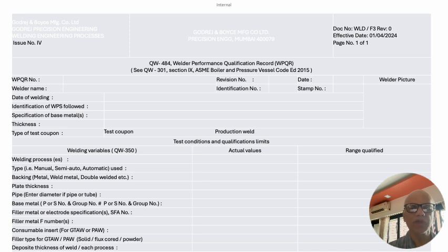Now the welder should be comfortable and should have confidence that in the given position or in the given setup, where there could be a possibility of a little lower root gap or a wider root gap, the included angle may be sharper or very wide, we'll have to somewhere butter it, or we'll have to do the overlay kind of welding.